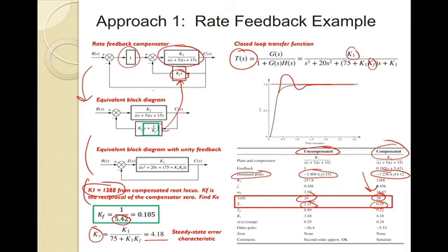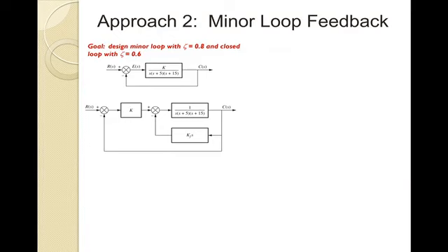Well, this is a step response, but when I would look at the error relative to a ramp input, you'll see that it's actually kind of similar. So what I'm saying here is you can actually get a better response, and you could say, well, does this really meet spec? Because I'm expecting 20%, I'm not seeing anything. But in terms of settling time, things look quite well. So again, I'll leave that for you to decide which is better, which is not. But we are kind of showing you an approach of what rate feedback can do for you, and see if this is something of interest.